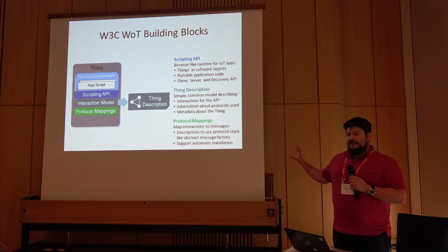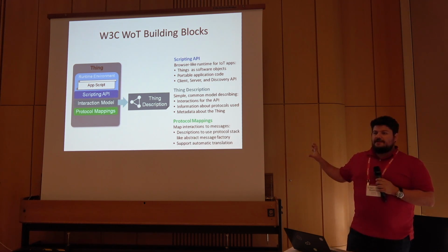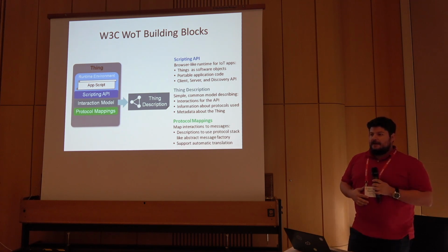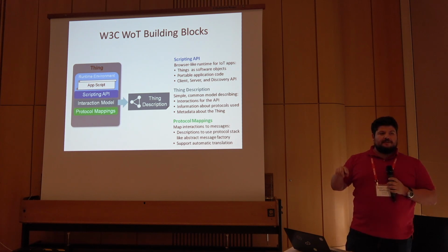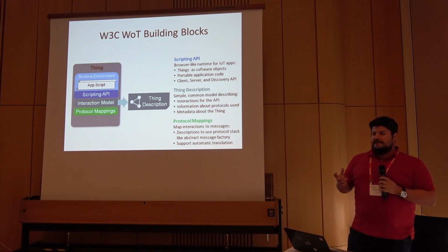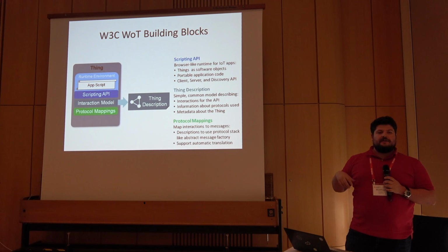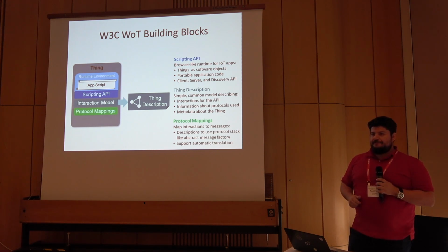And with these mappings, it also becomes easier to implement gateways that should bridge to different ecosystems. We, for instance, have a BACnet gateway that can discover whatever BACnet object is available in a specific network and automatically creates these thing descriptions so that clients for the Web of Things can directly interact with that. So they have no notion about BACnet, but they can learn how to interact with these different objects or devices that are available in the environment.